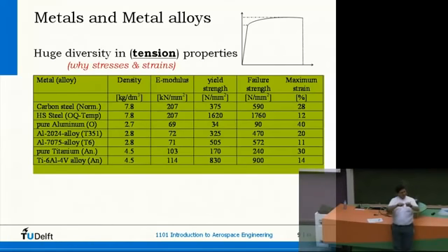Let's say we are talking about tension. We're pulling at a material, so it has a certain force divided by the area, ending up with a certain stress, but the bar also has a certain weight. Take whatever material has the lowest density, so for the same area, it'll have the lowest mass. Just taking the material with lowest density? No, not for just that application. You have to take some parameter which has the performance and the weight in there.